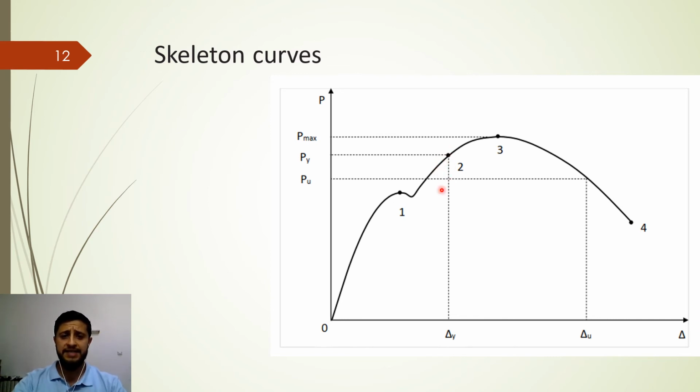Third, the elastic plastic stage, from point 2 to point 3. Stress of the steel section also increases with the increasing displacement. Point 3 indicates the peak lateral load of the composite column. Finally, the last stage is when the curve slopes from point 3 to point 4.